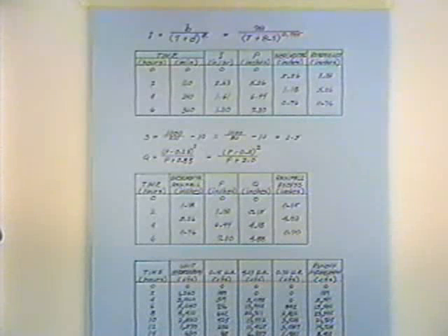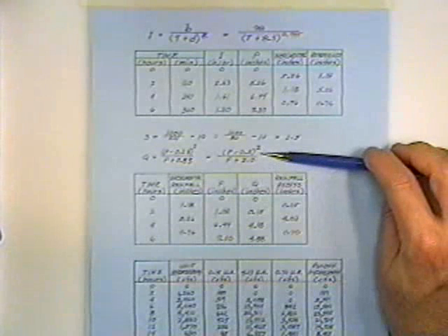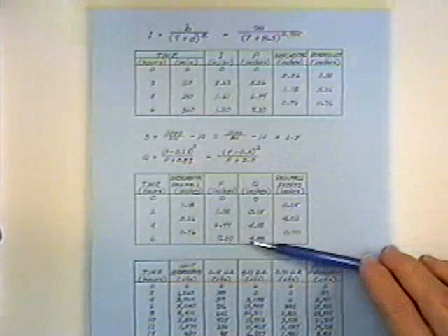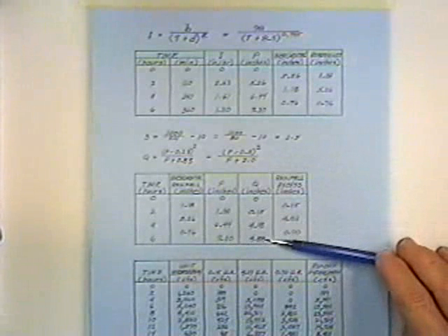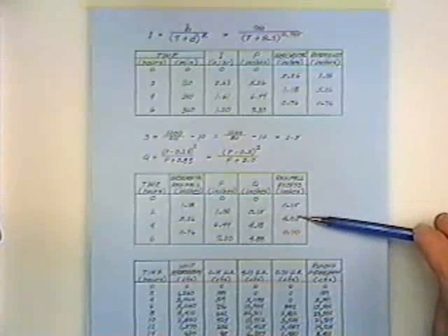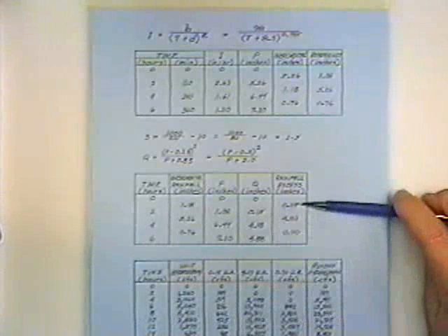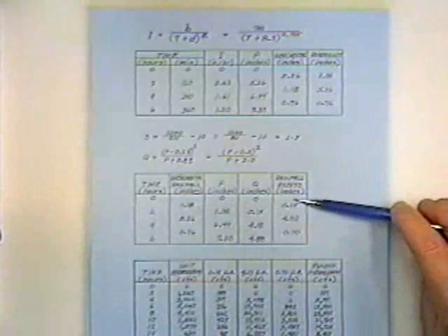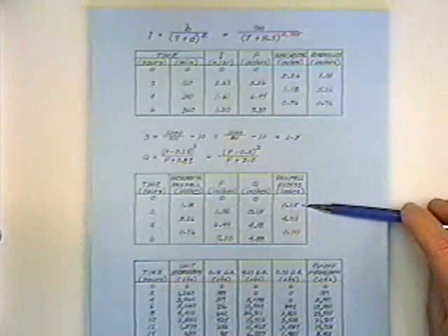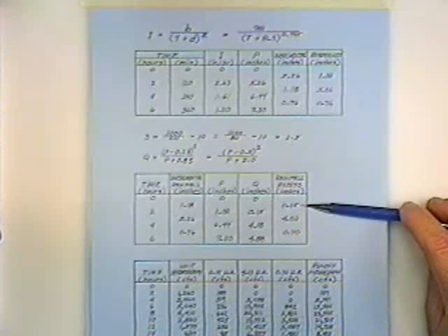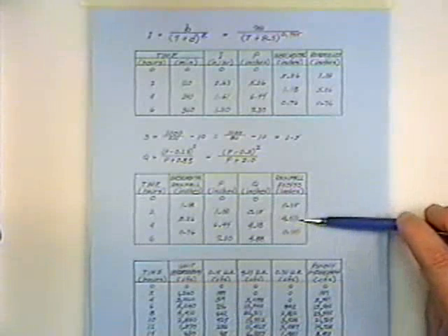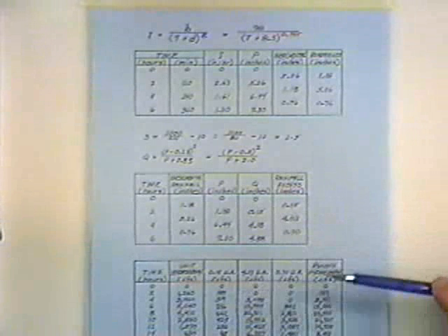The unit hydrograph applies to direct runoff volume. So we use the Soil Conservation Service equation that we looked at previously, and we take cumulative precipitation volumes and compute the corresponding cumulative runoff volumes, and then take the increments of runoff volumes. For the first 2 hours, we're saying we've got 1.18 inches of rainfall. It results in a runoff volume of 0.15 inches. And then we ratio the unit hydrograph ordinates in proportion to that to get a resulting hydrograph. Second 2 hours, we got that volume. We ratio unit hydrograph ordinates to get a discharge hydrograph.